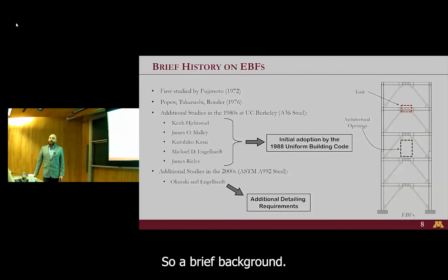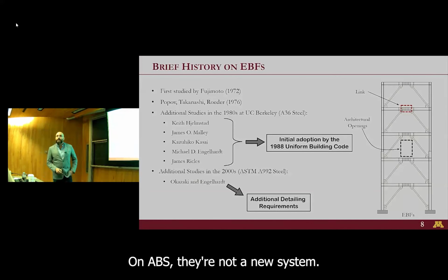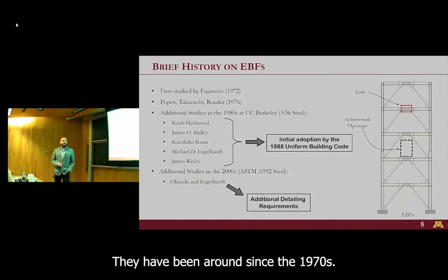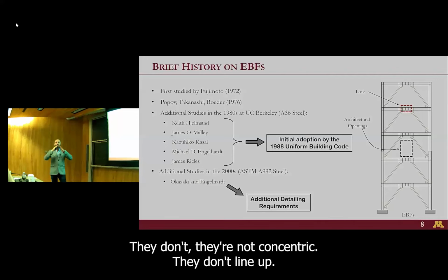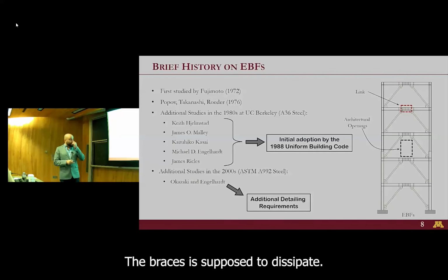So a brief background on EBFs. They're not a new system. They have been around since the 1970s. The idea is that you have a portion of the floor beam between the 2 braces that would... eccentrically braced frame. Yes, so that portion, I should have said that. The portion of the beam between the 2 braces, so the braces are eccentric. They're not concentric. They don't line up. So that portion of the beam between the braces is supposed to dissipate the energy.